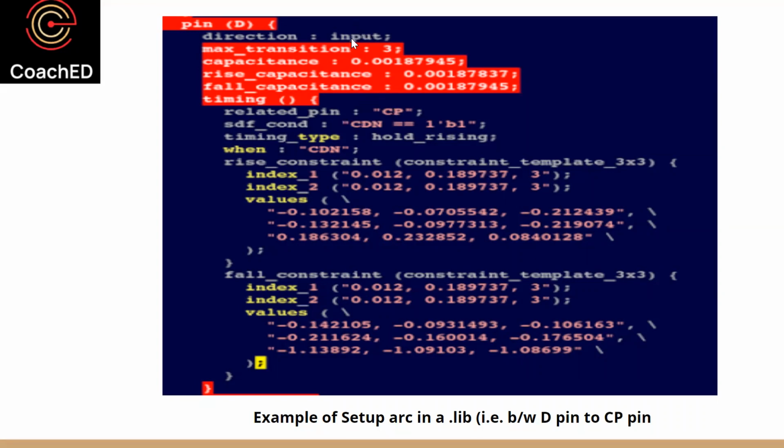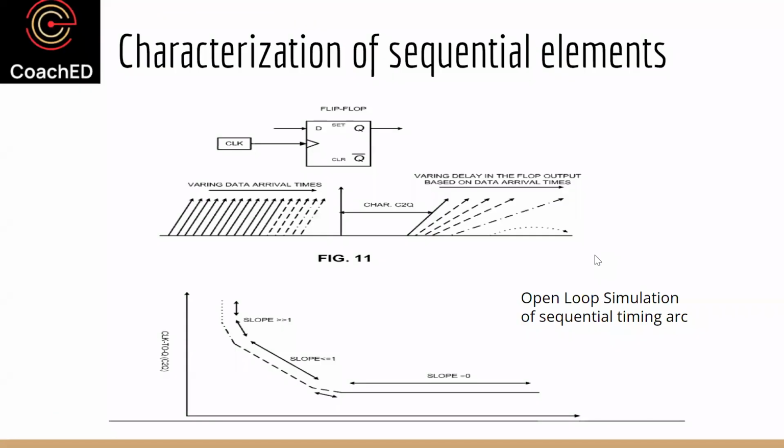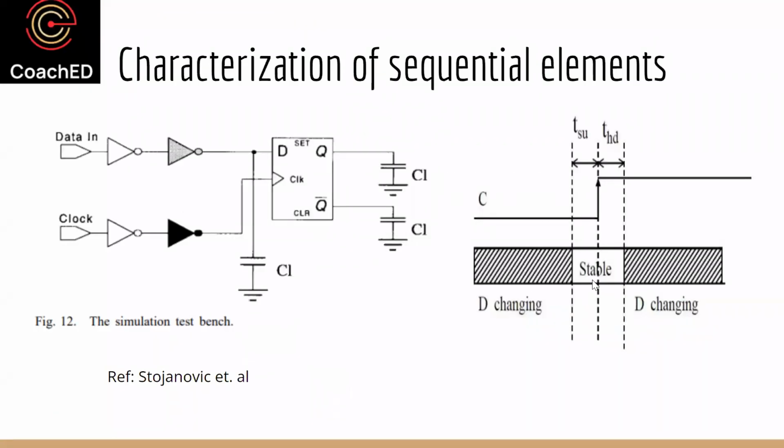So with respect to the clock pin, the input pin needs to meet certain timing. What is that? And here, which timing are we talking about? We are looking at hold. What was hold? If you remember, hold was how long you need to hold or retain the old data for the output to be stable. That means it is after the clock edge.